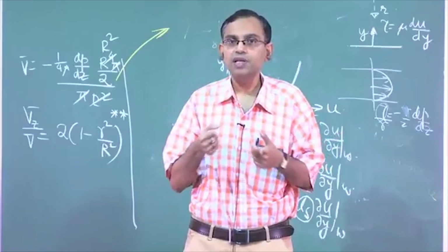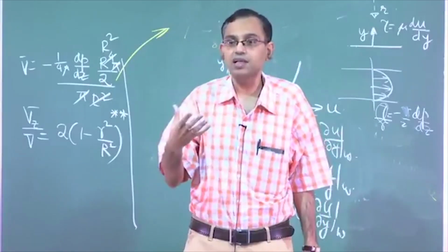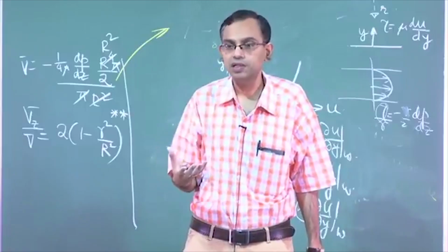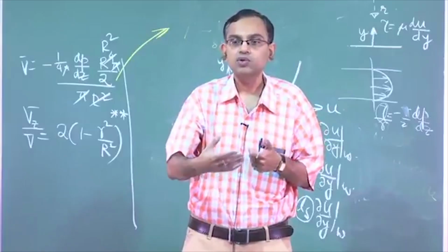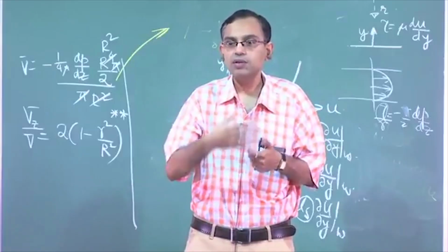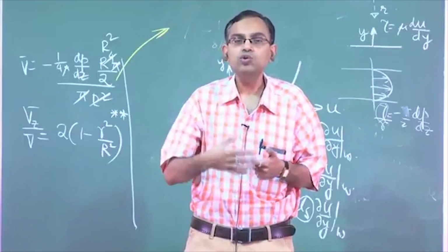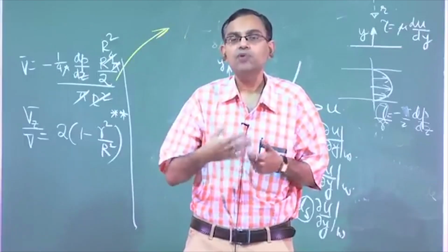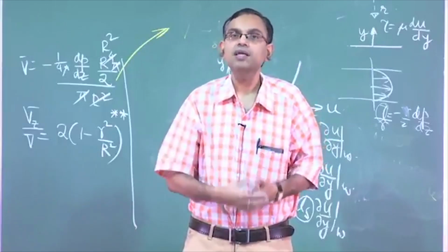Instead of creating a positive displacement pressure gradient, you can use surface tension to generate the equivalent pressure gradient, because surface tension is a beautiful force at small scales. So in our next lecture we will see what surface tension is and how it can be used to manipulate a flow which is fundamentally pressure driven, but the pressure gradient is created by surface tension.